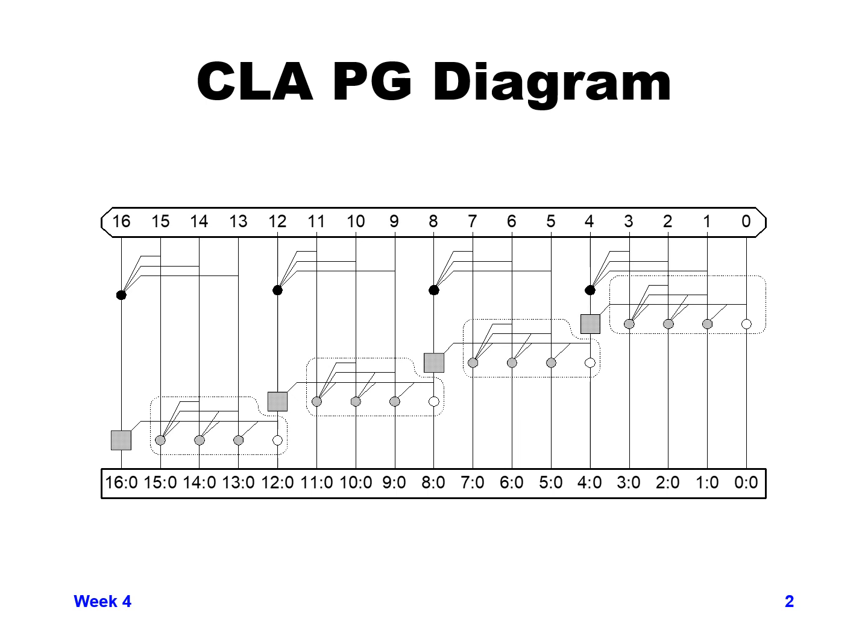So you can see the total time delay through this particular carry look ahead design would be the black carry look ahead complex logic at bit 4 plus a similar type of logic at bit 15 at the end.